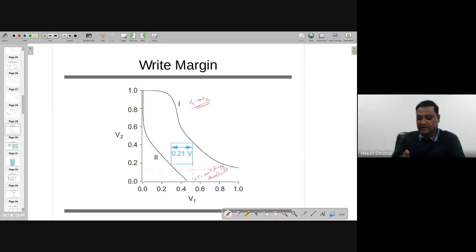And your output remains below the switching threshold so that it can qualify the logic 1 or logic 0 efficiently. So here you can see you generally have a good write margin. It's all depending on how you are designing the access transistor, the driver transistor, and the PMOS transistor. As per the thumb rule, D1 and D2 should be higher. The next higher has to be A1 and A2. And P1 and P2 have to be the smallest ones, right?